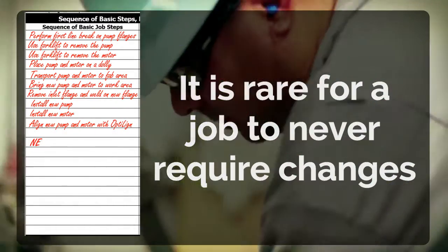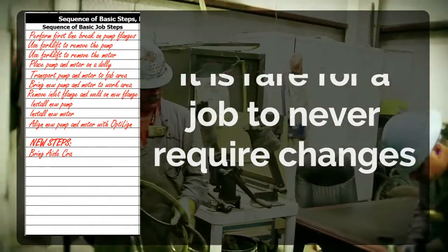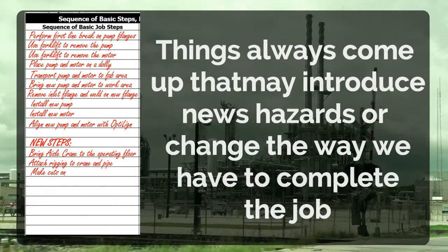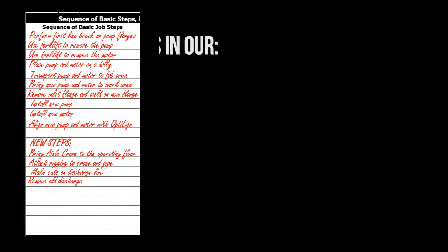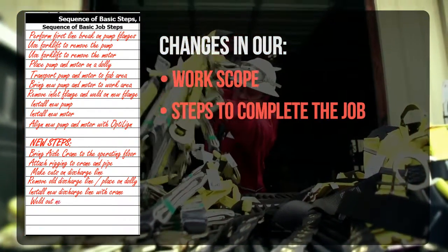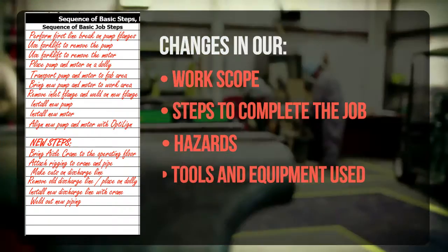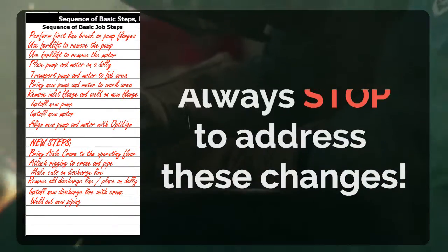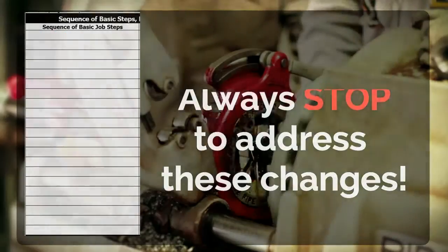For example, you may find out that the outlet line on the discharge pump is completely corroded, and you will have to remove it with a crane. This creates changes to the work scope, steps to complete the job, hazards, tools and equipment, and precautions in order to complete the job. Always stop to address the changes.